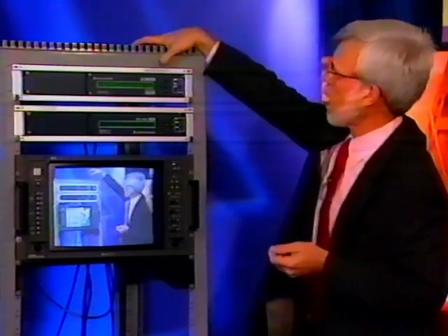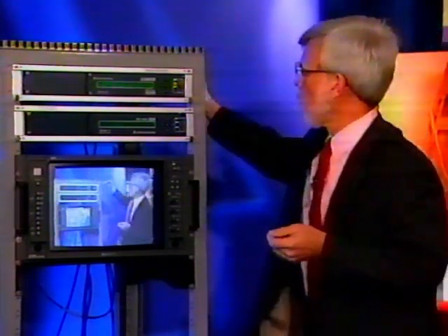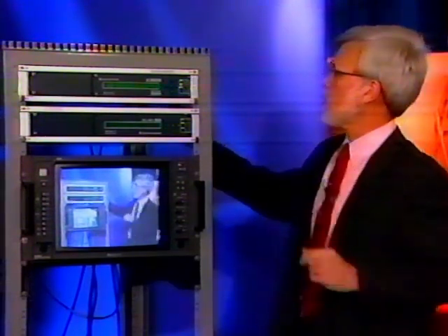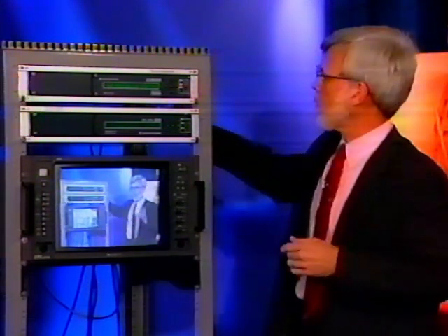It had cold air blasting down on it. It got very cold on the top. It was very warm on the bottom from the air coming up. And the difference in tolerance on the components was enough that it just wouldn't operate properly. It's a simple fix. If you have that situation, put a piece of cardboard, cloth, styrofoam, anything you can find on top of the unit, just so it doesn't get that deep freeze from the air coming in from the top.